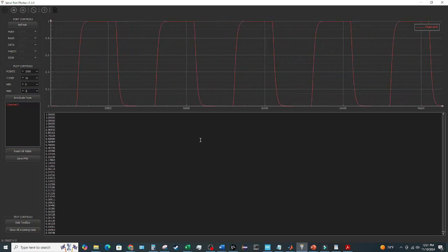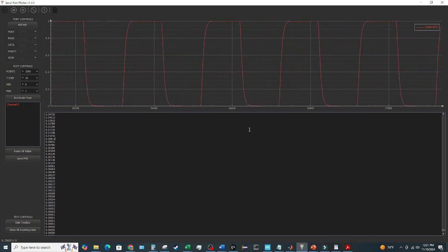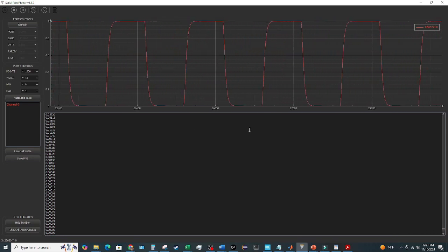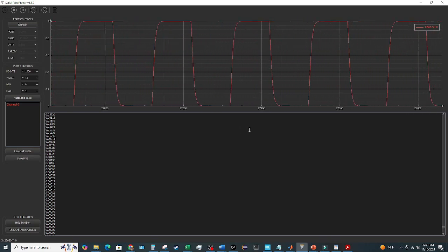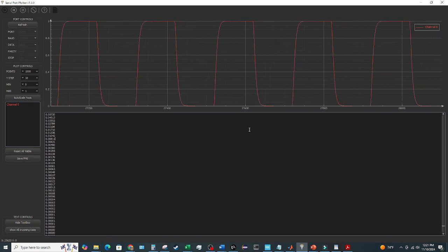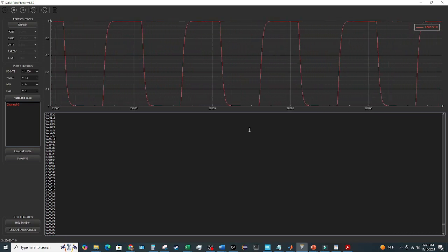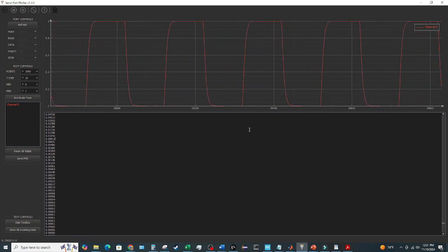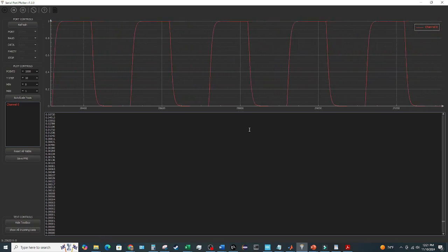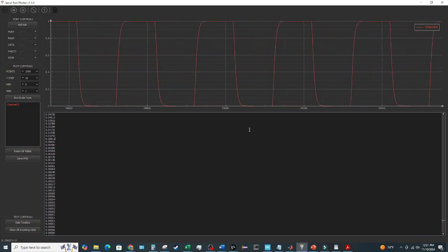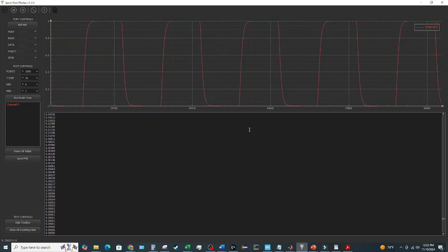All right. So now you can see we must have actual real roots that are not complex conjugates. So we basically have no oscillation. The system is overdamped. That means the roots are real and on the sigma axis. So it's like a double root on the real axis, and we have no oscillation, definitely stable. So we've changed it so the quantity in the radical for those roots is now a real number.